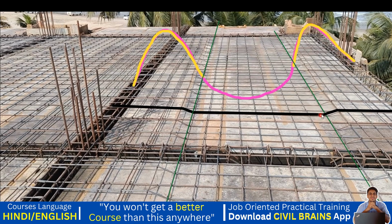In the same way, these are your distribution steel, which we have given from the temperature and shrinkage point of view. The main agenda was something like this. That is why we have taken the bar to the top on either side, and this is my bottom reinforcement. This much is understood?